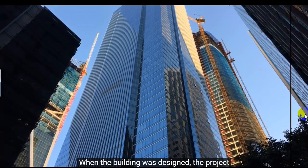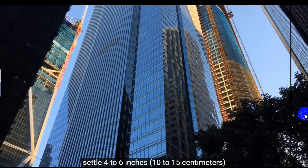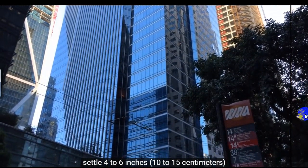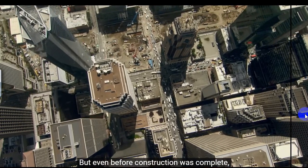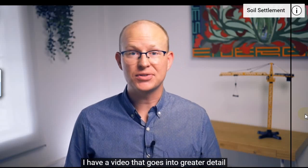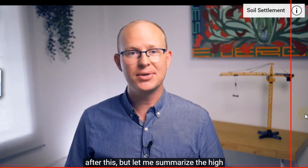When the building was designed, the project geotechnical engineers predicted that it would settle 4 to 6 inches, or 10 to 15 centimeters, over the structure's entire lifetime, mainly from this layer of Old Bay Clay below the bottom of the piles. But even before construction was complete, the building had already settled more than that. I have a video that goes into greater detail about soil settlement that you can check out after this, but let me summarize the high points here.